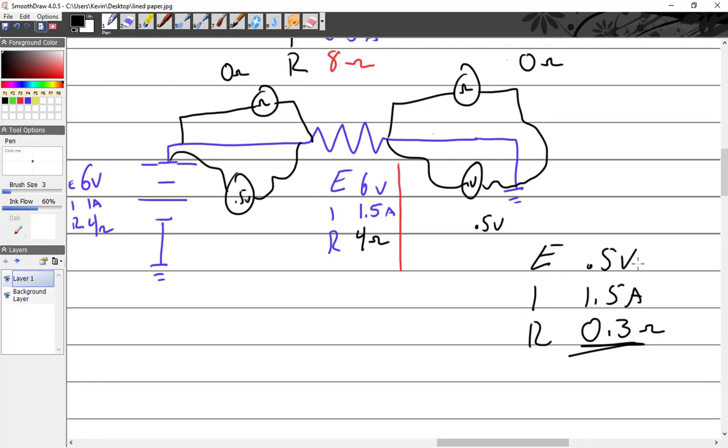When you're working with these batteries, you're going to be having 10, 15 amp draws. I think it's something like 10 amps. Well, at 10 amps, things start to multiply out. And you start to see effects that you didn't see before. So yeah, maybe you have a negligible effect with your wires when you're working with your tiny batteries. When you get big batteries, you get big effects, but you can't see it with your ohm meter.